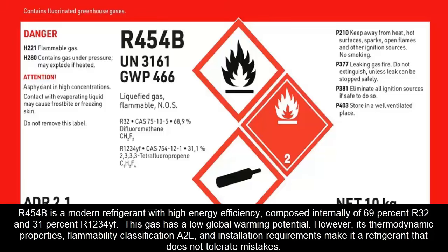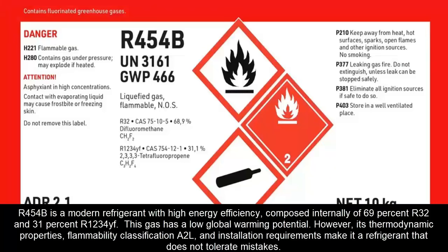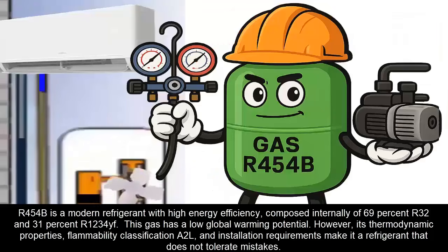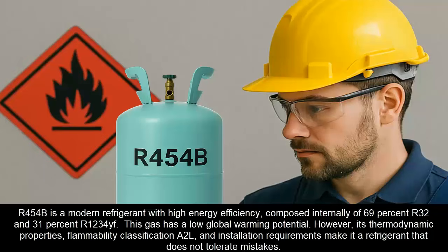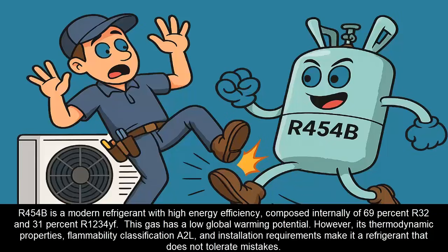R454B is a modern refrigerant with high energy efficiency, composed internally of 69% R32 and 31% R1234YF. This gas has a low global warming potential. However, its thermodynamic properties, flammability classification A2L, and installation requirements make it a refrigerant that does not tolerate mistakes.